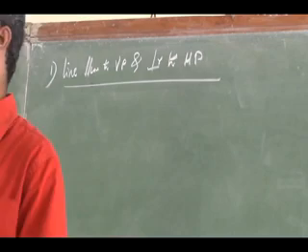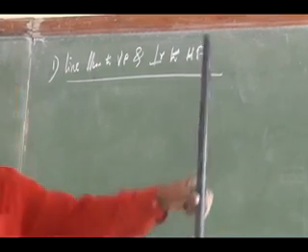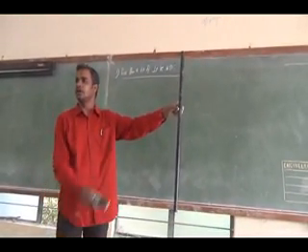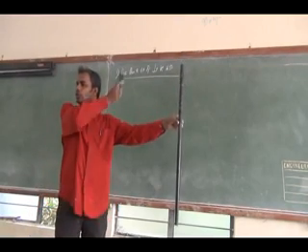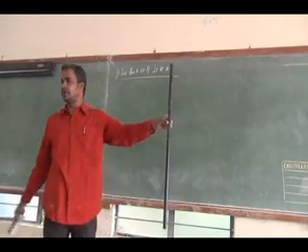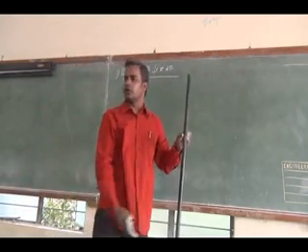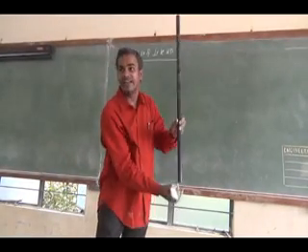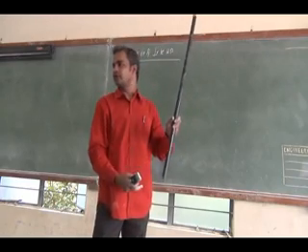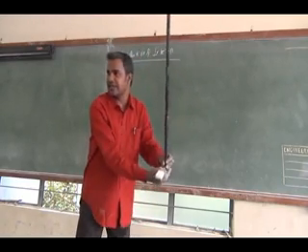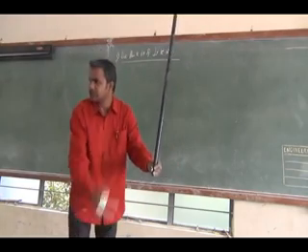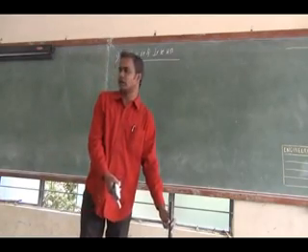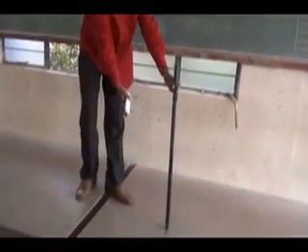Parallel to VP and perpendicular to HP. So here, this is the orientation, you know, right? What I am going to deal with. The line is parallel to VP and perpendicular to HP. In the problem, the line length will be given, and one end position is given. The line will have two ends, and one end position will be given. That end is definitely in the first quadrant, above and in front of. In the other case it can be touching the reference line. The above distance is 0, but the in-front-of distance of one end will be given.